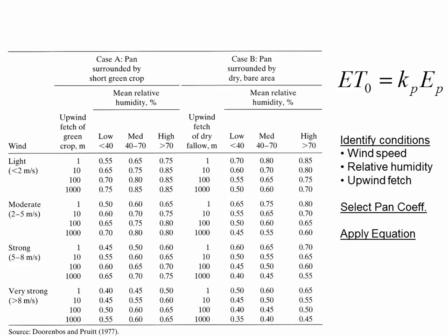So where we're doing that here, where we're saying we maybe need to have 94.5 millimeters per month of water to keep grass alive, that's just a ballpark estimate, because some days are going to be more windy and less humidity, which means you'll have more water that needs to be added. Other days there will be no wind, it'll be very humid and maybe cloudy, and so there would hardly be any evapotranspiration at all. But it's good for an estimate anyway. It's better than nothing.